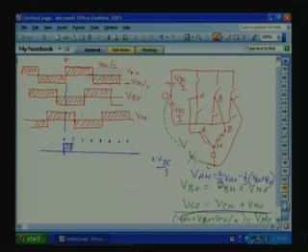Then our 2 by 3 VA0 is again Vdc by 3, like here. So, Vdc by 3 plus Vdc by 3 will equal 2 Vdc by 3. So, it will go up to 2 Vdc by 3 from here. Now, if you see, it repeats like this. This is the positive half cycle, then this is the negative half cycle.